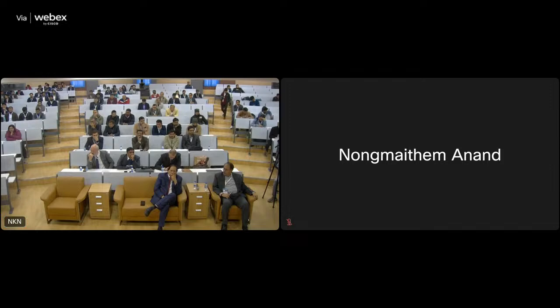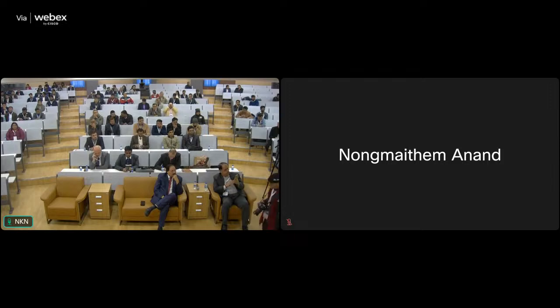And you see, after the blast, what do we do? Geologists go to the face, map the geology, map the joints. After that, they calculate the Q value, and then the support is decided. So when we collect the Q, the rock mass is also damaged because of the blasting or because of the loosening of the zone. And we have seen a change in Q from 4 to 1. Because of the stresses mobilizing from the face towards the tunnel, there are chances of some cracks from the loosening. So those cracks on the roof are also going to be cemented because of the rock bolt grouting. So we expect an improvement in the Q value.